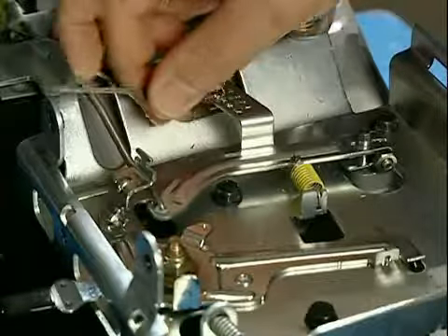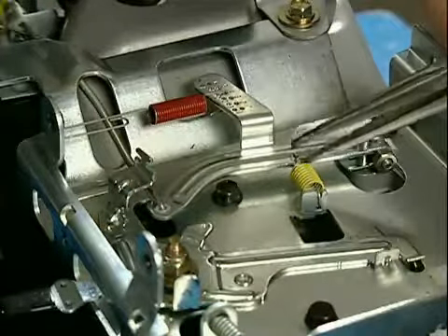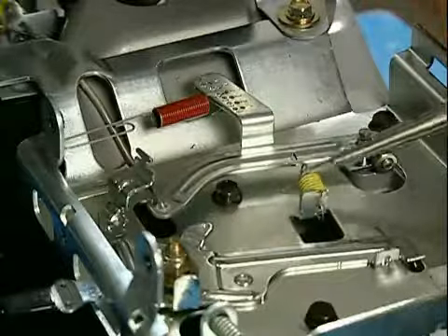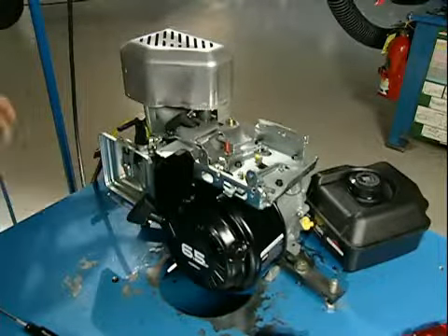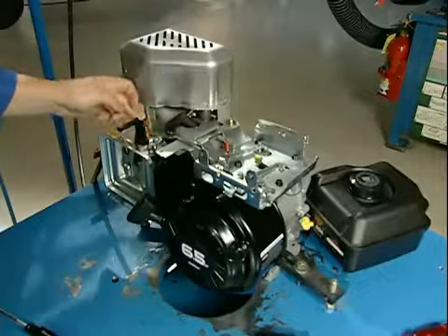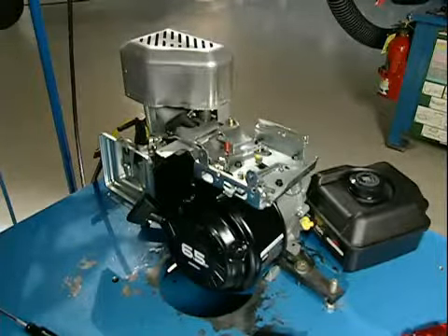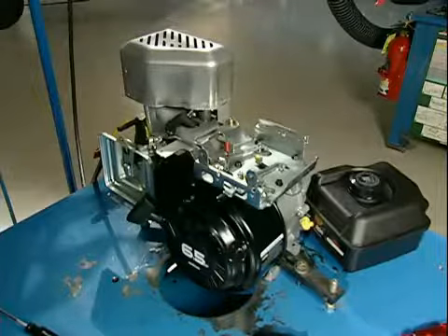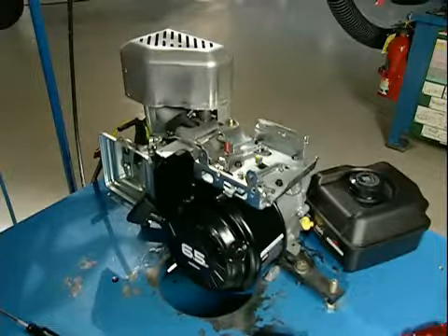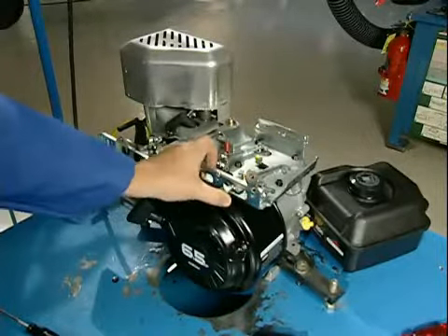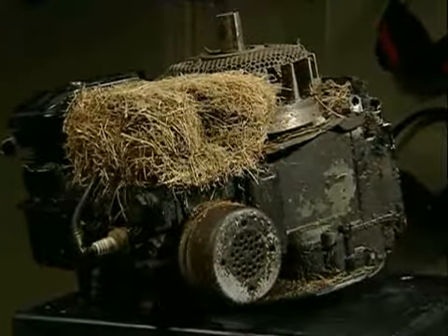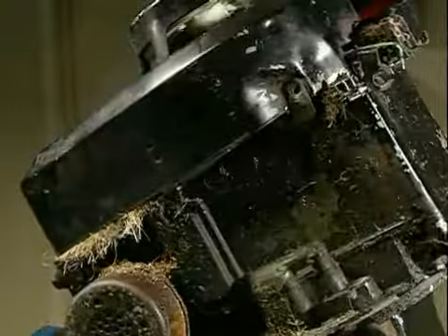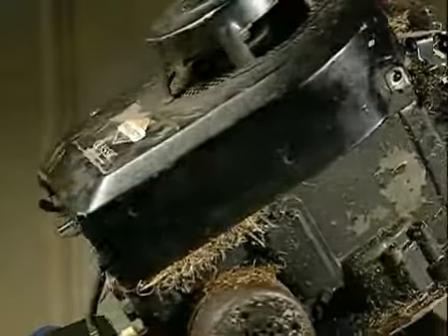Perform a static governor adjustment. Remove or unhook governor springs. Start engine. Quickly move throttle shaft toward the wide-open throttle position. If the internal governor gear assembly is functioning, the throttle shaft should immediately return to idle. The problem will be external. On an air vane system, you should routinely check for a mouse nest or debris blocking the air vane, as well as air guides or baffles missing, allowing air to escape.